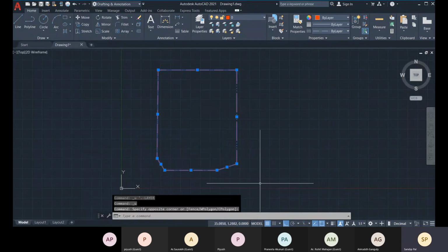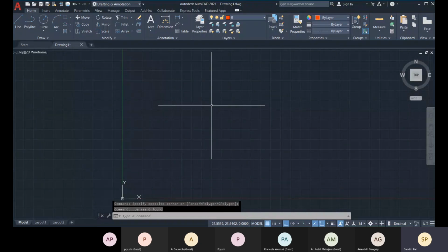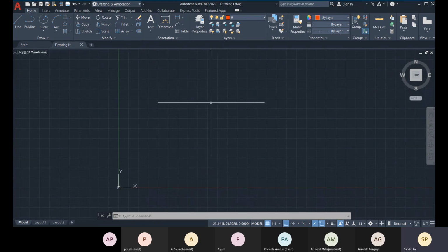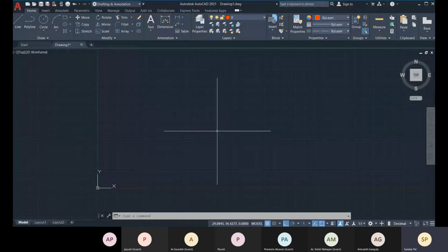Now we will learn about what a layer is. Here you can see layers, like if you place different sheets vertically, all those layers are stacked vertically, and this way you get different layers. But here we don't place like that; here we place objects with different properties. With layers we get better visibility. At a single glance we can identify different objects with different properties, and we can better control our objects in the projects. With visibility, freeze and thaw, and other options, we can control our object visibility and work efficiently with the layers.